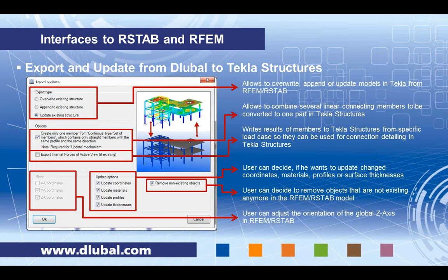On this main girder you have additional cross beams that connect somewhere along this main girder as secondary girders. And when I analyze it inside Dlubal software or typically all other software, then you have to make a connecting node where those intersection points are. So inside you have actually 3 analytical members maybe where there is only one major part in Tekla Structures.